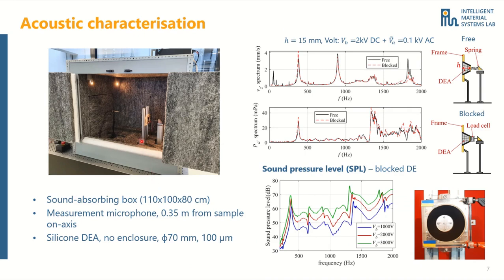We then placed our sample in an anechoic box that we built in our laboratory, and we measured the sound pressure obtained by exciting the membrane. This black line is the average axial velocity spectrum, and down here is the sound pressure spectrum. As you can see, the sound pressure is close to zero in the pumping region. No sound is actually generated by the pumping motion because its passband falls in the low frequency range, and the device only starts generating sound when the structural modes are excited.